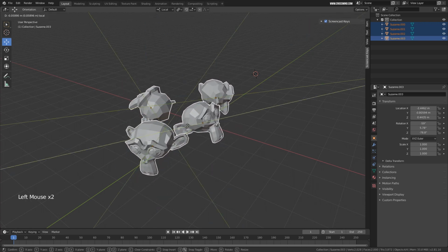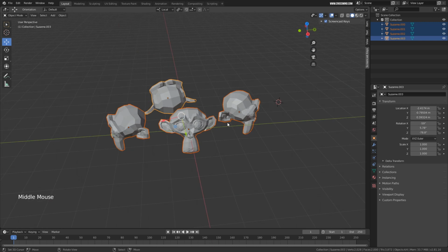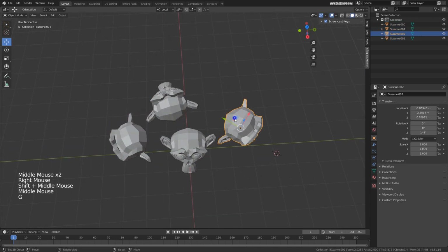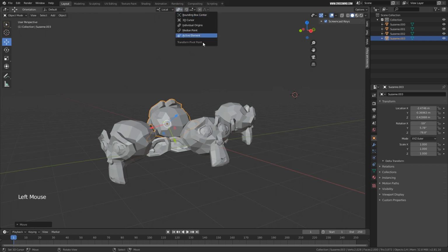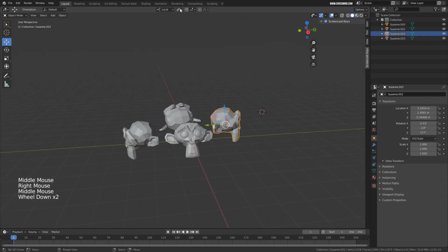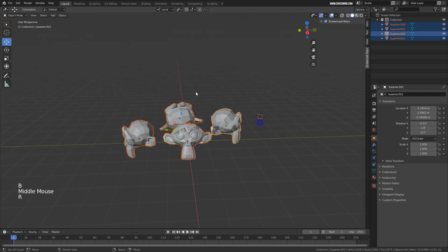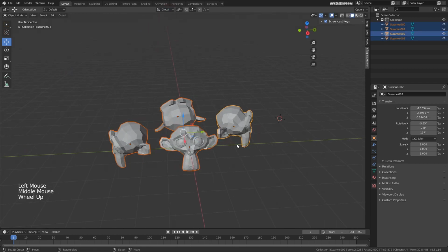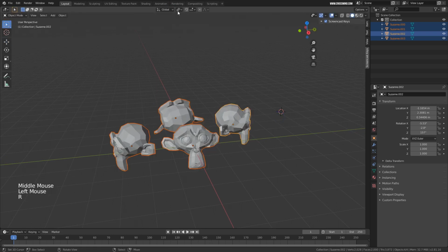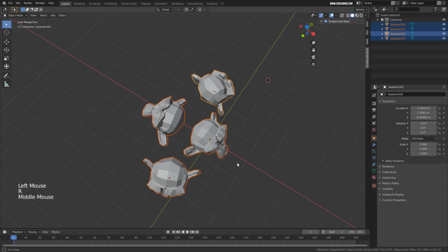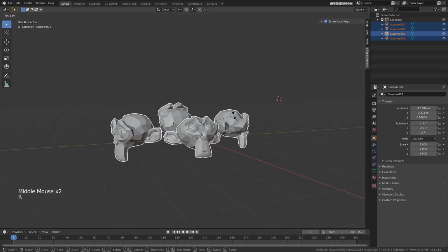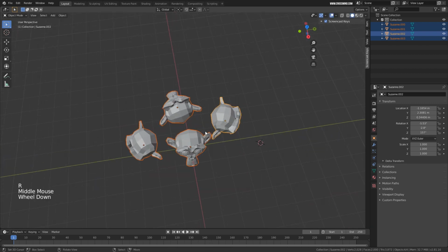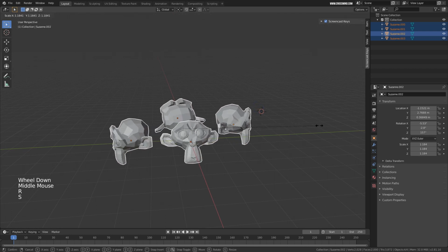So these are very important if you are animating, and also if you want to place models more effectively. I'll encourage you to try these out as well. And also there are a few options for transform pivot point. What transform pivot point means: if you select everything and try to rotate it, I'll go back to global. Now if you select everything and rotate it, when you make any transformation, it takes the center of the selection as the average point and makes the transformation from the center, especially the rotation or the scale.